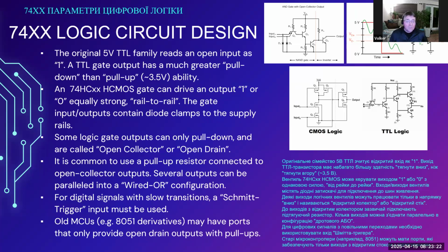Old microcontrollers, some 8051 derivatives, they're still around. 8051 still exist. And some ports in the 8051 microcontroller, there are no push-pull outputs on those ports. I think it is at least one port of the typical ports in the 8051.